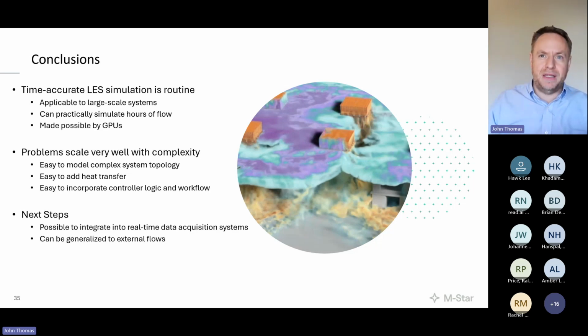When you have that holistic view and can see how all these physics are interplaying and are interconnected, it's very compelling to see, oh, what if I just change the vent? What if I change the PID feedback control? What if I change the position of the return, as it were? When you can make these adjustments without having to rip the guts out of your model every time, you become very efficient from a process simulation standpoint and as a CFD engineer.